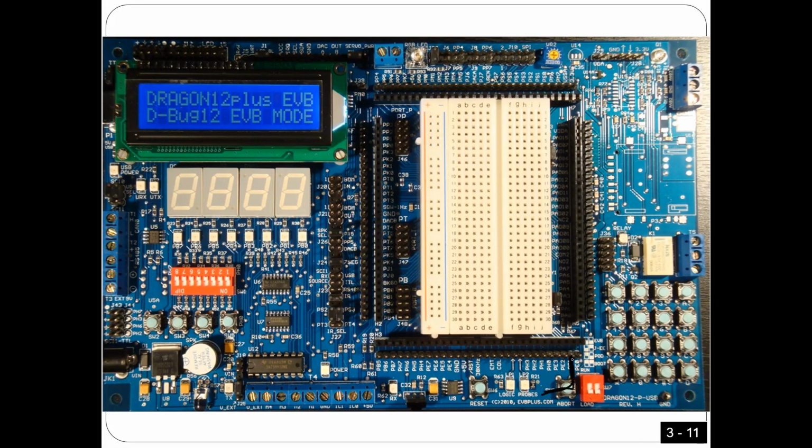So what you have to do is connect an external wire from here, from BE1 or BE2, whatever IRQ is, and then connect it to, for example, BH0. I can connect a wire to BH0, and after that I can use this push button here, guys. Every time I press this push button, BH0, there is a signal like this. This signal is going to be generated in port H, and this wire is going to connect it to IRQ to trigger interrupts. Okay, that's what I meant.